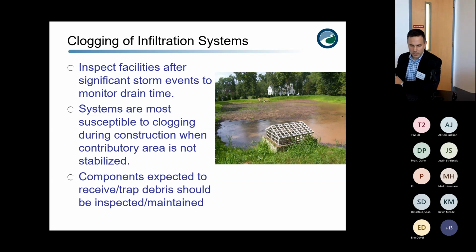So we want to be able to not put in that infiltration layer, like the bioretention media, for example, until we have that whole area stabilized. So typically we'll build these, we'll roughen the grading for these basins, for example, on a development site, and we'll leave maybe 2 feet to the final subgrade. We'll let that function as a sedimentation basin, and then we remove everything that's settled over time. We dig an extra 2 feet out until we get to clean soil.